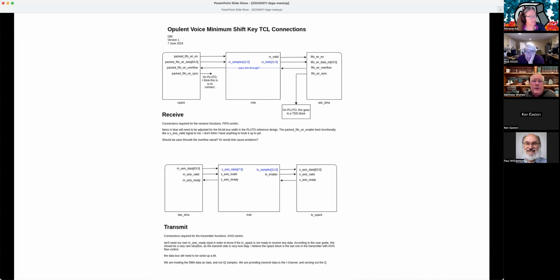So here, the decimator, we might need the decimator here because in the Costas loops we do have the accumulators. And those accumulators, if we're 60-plus times oversampling, could get pretty large. So the decimator might be helpful in the receive path. I think, if we're using the DSP slices, even if they get large, I don't think they'll get 48 bits large. So, if we wanted to save the resource, we probably could. So that's kind of an open question.